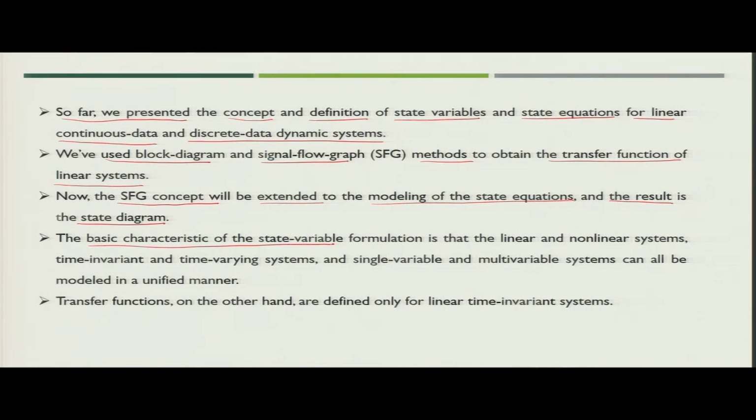The basic characteristic of state variable formulation is that linear and non-linear systems, time invariant and time varying systems, and single variable and multivariable systems can be modeled in a unified manner, while transfer functions on the other hand are defined only for linear time invariant systems. So, with this we can close our today's discussion. We will continue our discussion while we start modeling the multivariable system, where you will see multiple inputs and multiple outputs and how you will analyze those sets of models.